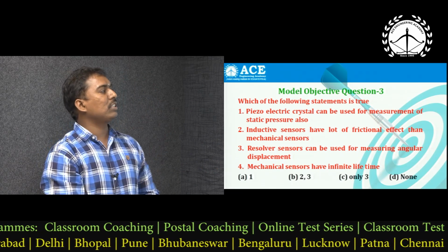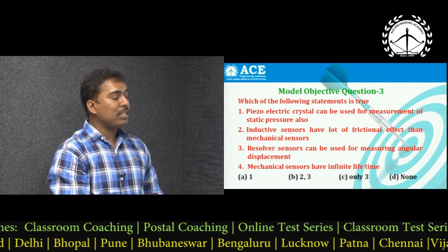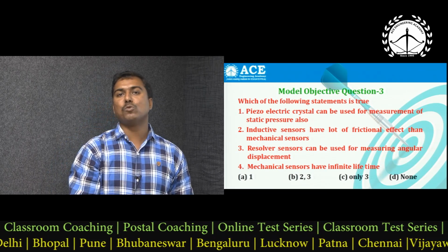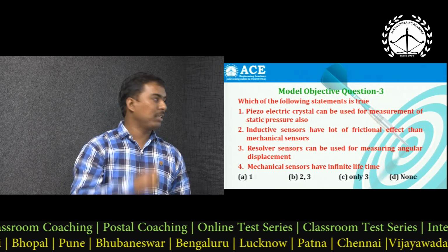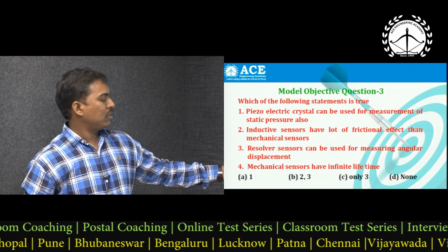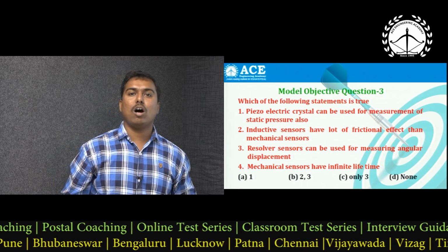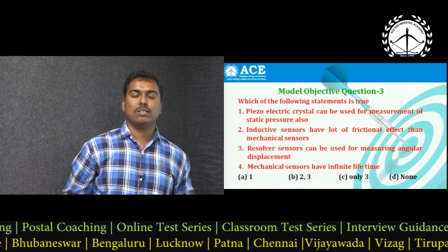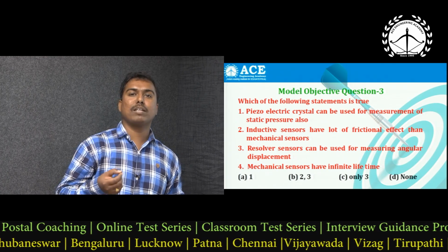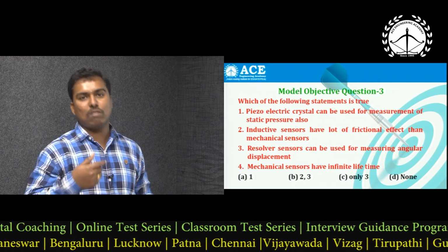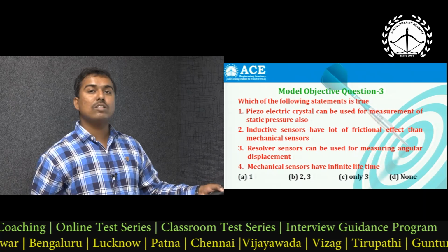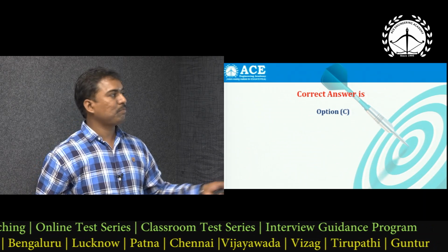And as I told, piezoelectric crystal can be used for measurement of static. No, it can be used only for vibration, dynamic. So definitely only the third statement, as I told, optical encoders and resolvers, these two are used for determining the position of a shaft, moving shaft. So the answer is option C.